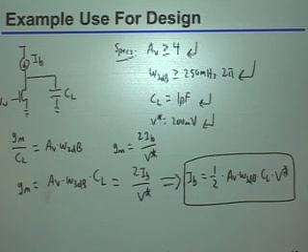Now, what is still missing in terms of you actually finally building this circuit? Yeah, so we haven't specified the sizing, and there's one other parameter that I never explicitly... The DC gate voltage. Okay, you're right. Although, actually, that's very much related to the sizing, as we'll see. Once I've specified V star, both the sizing and the DC gate voltage will pop out. Okay, and we'll see that a little bit later on.